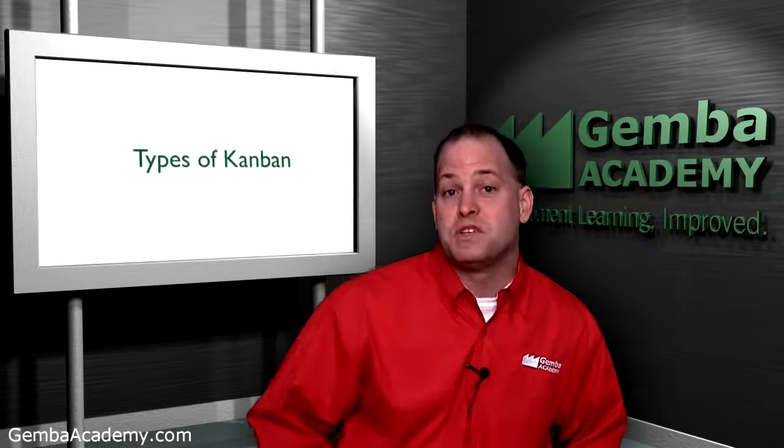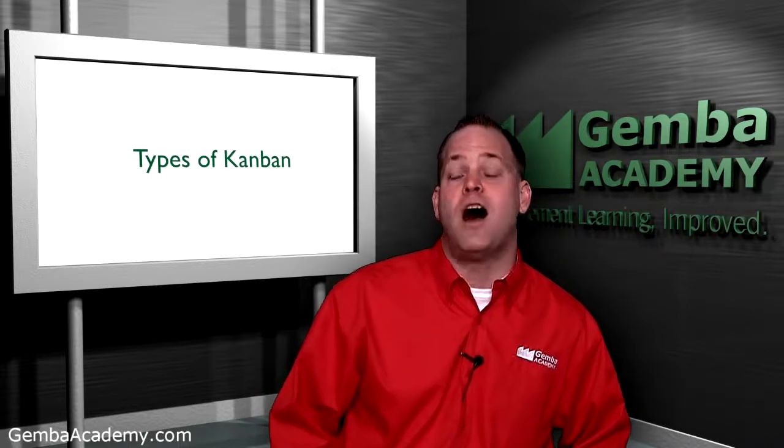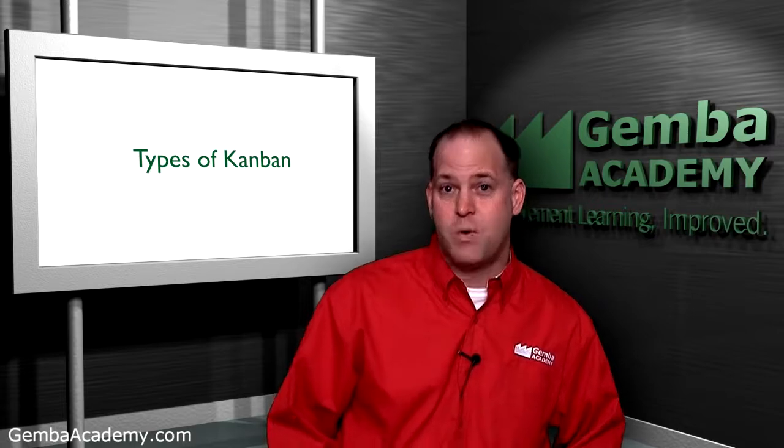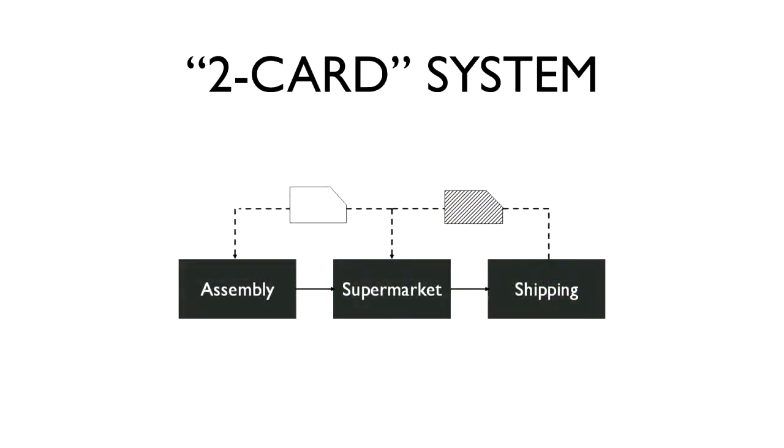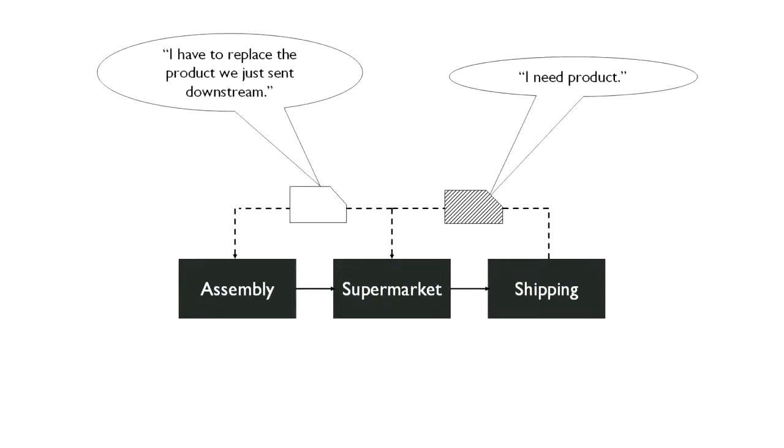Alright, well, to wrap up this first overview module, let's learn about some of the most common types of Kanban. The first type of Kanban is the classic two-card system, where production and withdrawal Kanban cards are used. In this example, we see a shaded withdrawal Kanban going from shipping to the supermarket. Now, this is a signal from shipping to the supermarket that it needs product to meet a customer request. Once a shipping clerk removes product from the supermarket, a production Kanban will be sent to the assembly department, signaling there's an item missing in the supermarket that needs to be replenished.